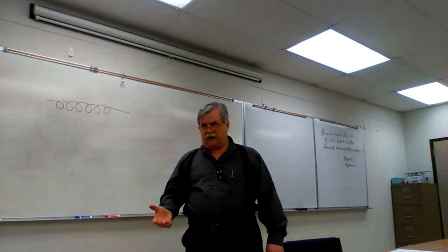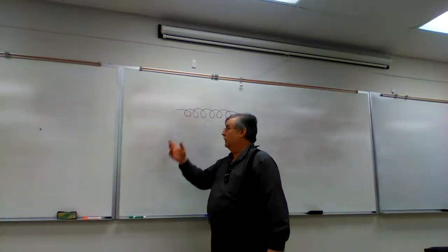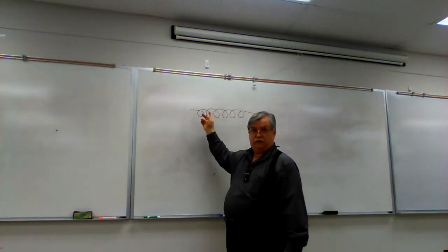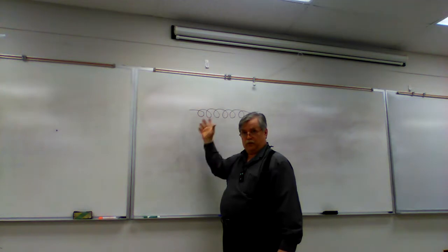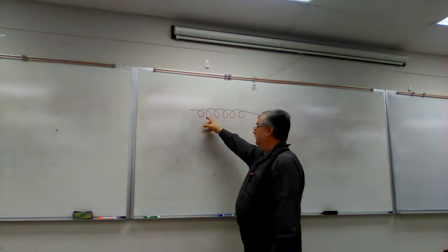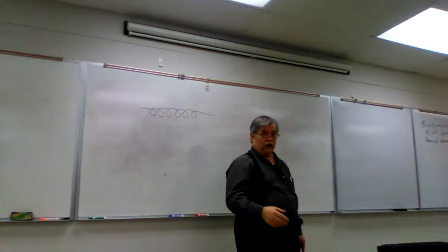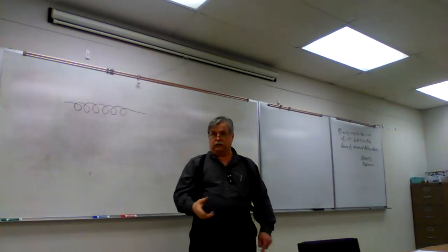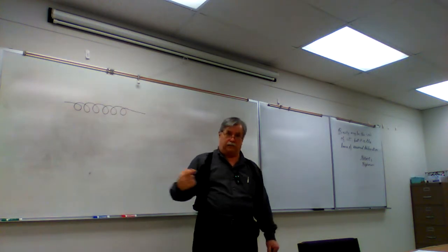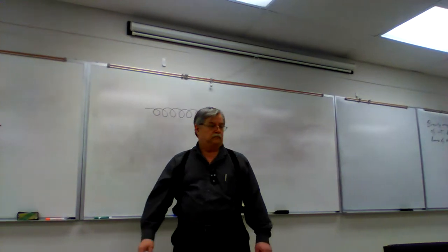We've already looked at Lenz's law. What happens with Lenz's law? The field that the current produces is going to intersect with all of its adjacent wires to induce a countercurrent, a counter magnetic field that will oppose the changing current. Right?